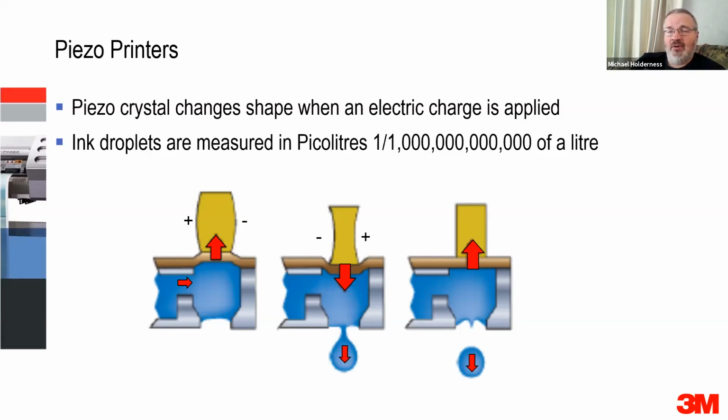So you will end up with a better looking ink drop, or a better looking print. The trouble with that though is if you go down in ink drop size, you need more ink drops to create the image. So it tends to slow the printers down. So you either need to run the printer faster, or you are going to get a slightly longer delay time because it's going to take longer to put that much ink down. Or you end up with more heads. Some manufacturers are putting more heads in there. Lots of different ways of doing it.